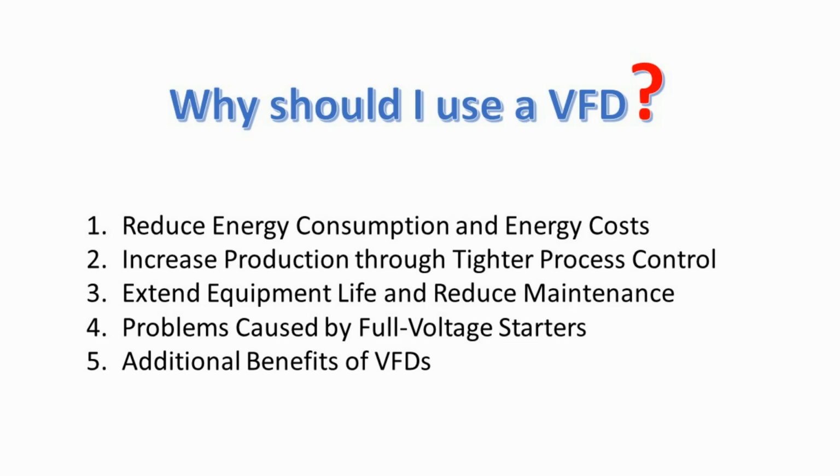Third one is extend equipment life and reduce maintenance. Your equipment will last longer and will have less downtime due to maintenance when it's controlled by VFDs, ensuring optimal motor application speed. Because of the VFD's optimal control of the motor's frequency and voltage, the VFD will offer better protection for your motor from issues such as electrothermal overloads, phase protection, undervoltage, overvoltage, etc.